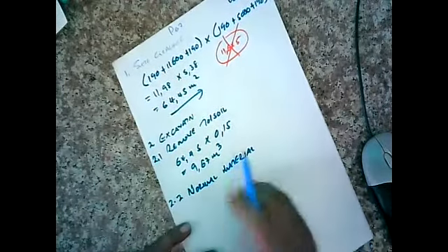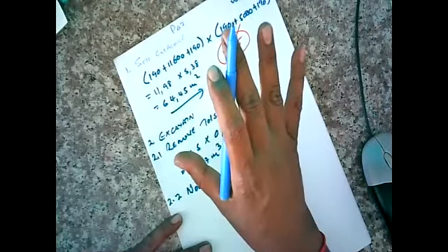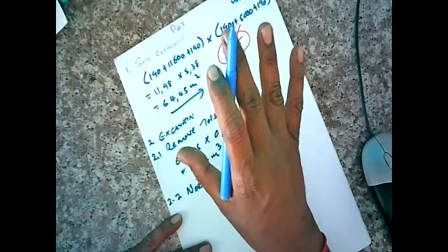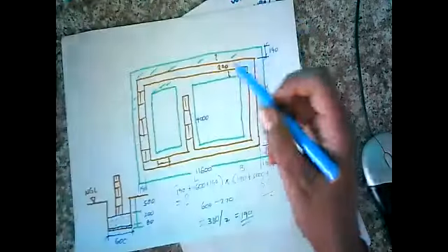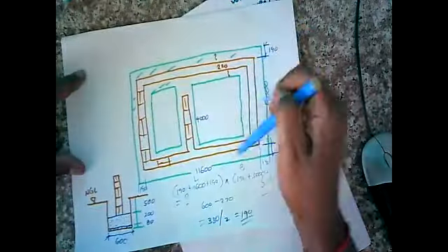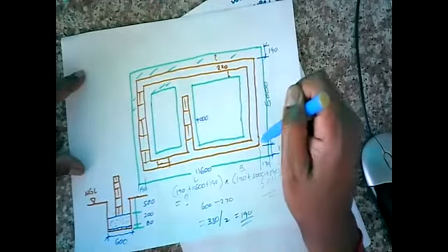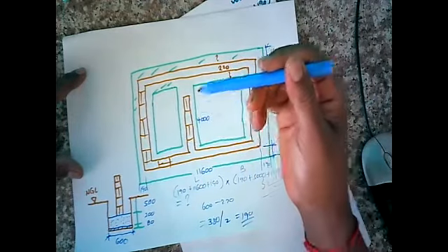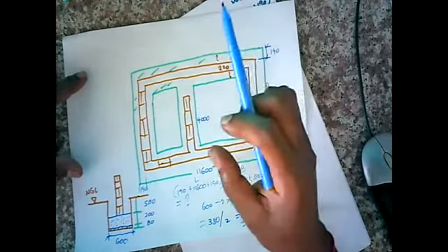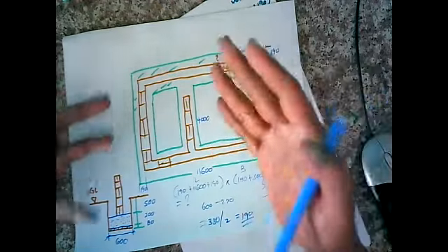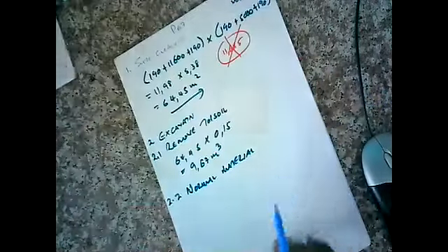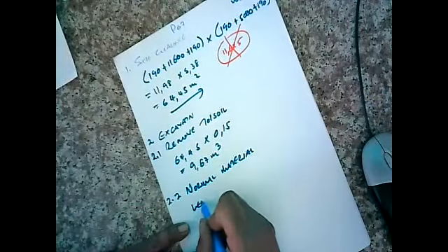All right, normal material. I need to find out what the perimeter is of all the trenches. What is the perimeter of all the trenches? If I know the perimeter and I know the depth and I know the width, then I have a volume, isn't it? Exactly. So the length, what is the length?